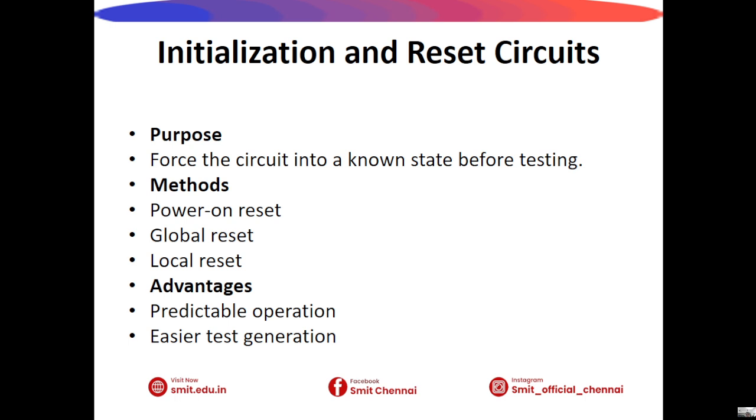Next, we see about initialization and reset circuits. Before testing begins, it is important to place the circuit in a known state. Reset circuits perform this function. A power on reset automatically initializes the circuit when power is applied, while global and local resets help prepare specific sections for testing.